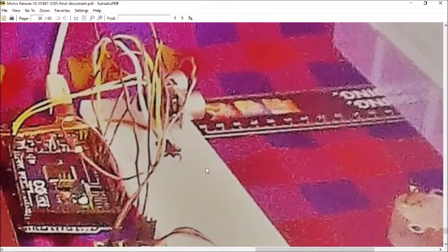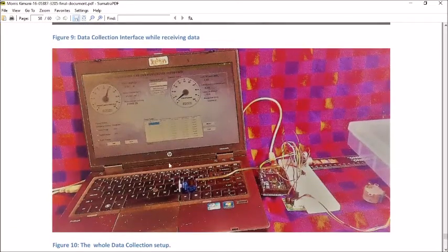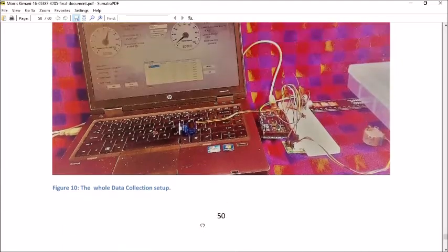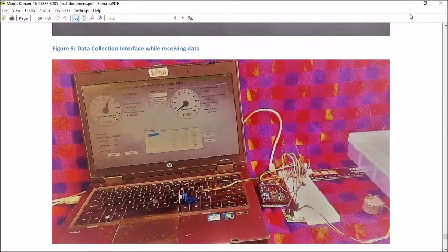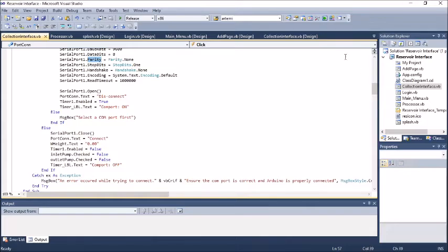So I'll just be inverting the readings so that I can get the results that I want. When the tank is empty, instead of us reading 30, instead of reading 3 meters, we're going to be reading 0. So there is some inversion that I did in the code. And I think that's what we're going to go to next, since we've already seen the interface.